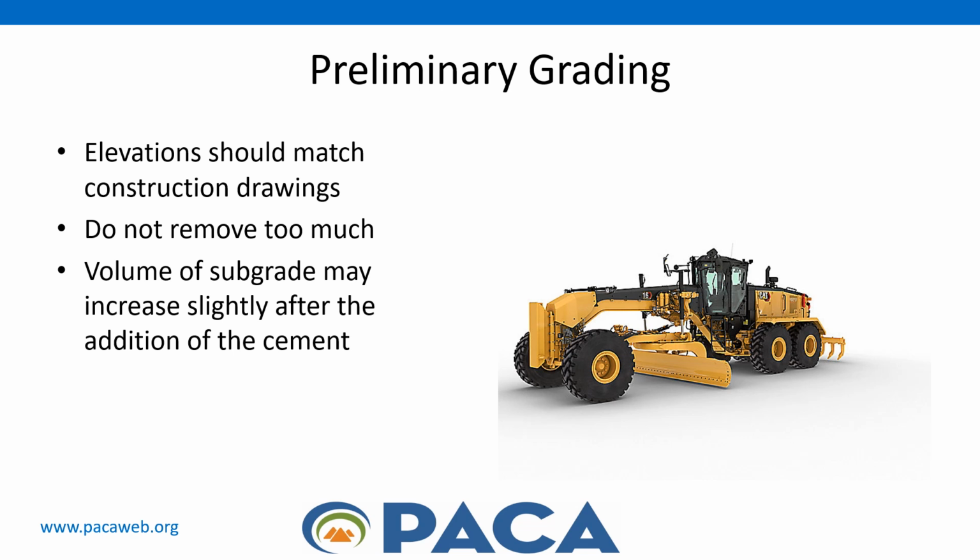The crown and grade of the planned roadway or pavement should be noted, and grading should be completed as necessary to match the construction drawings. Now, take care not to remove too much material at this stage because it's easier to remove material than add after the cement is applied.